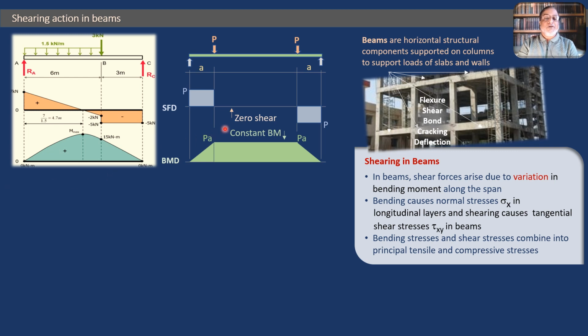So this bending moment diagram clearly illustrates the variation of bending moment and its relation with shear force. Now we can say that for any cross section between these two loads where the shear force is zero, this portion of the beam is undergoing what we call pure flexure, or pure bending. Otherwise it is not pure bending; it is bending mixed with shear.